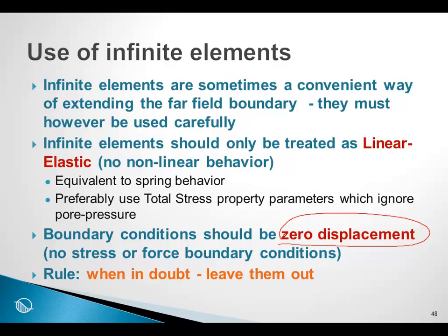So generally, we start without infinite elements, and then toward the end of a modeling exercise, we may add the infinite elements to see whether it makes a great deal of difference on the solution. But generally, the rule is, when in doubt, leave them out. So don't use them without understanding the full implication of what they are all about and how they behave. And if you're in doubt as to the behavior of the infinite elements, you can extend the mesh to the left and right rather than use infinite elements if that is more comfortable for you.